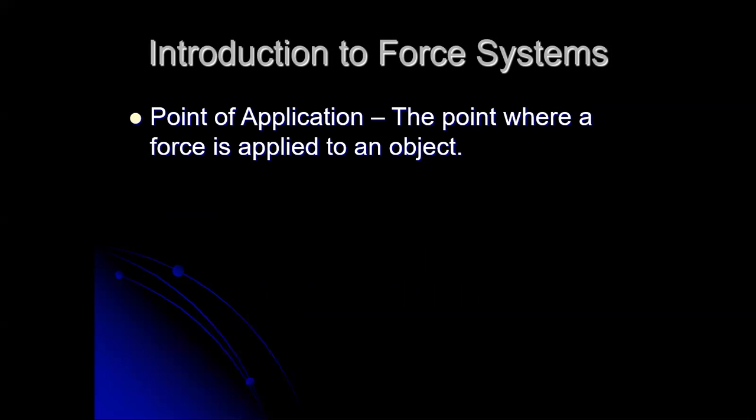Now, that's not always true. In fact, it's never really true. We can never really hook a force right on to, say, a single molecule or a single atom or something like that. What we deal with in reality are what we call distributed forces. But it's a lot simpler to think of point forces. So in all of our problems that we're looking at first, we'll be considering just point forces. And point forces are not a bad approximation in most situations.